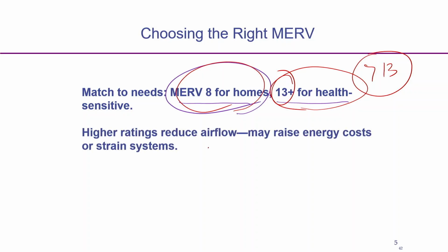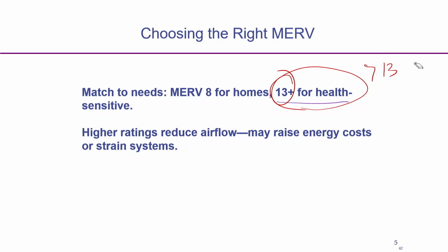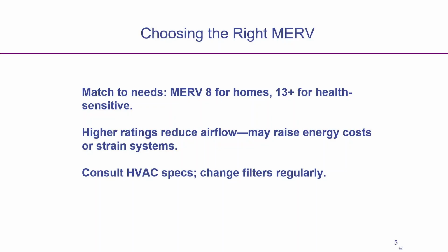A higher rating reduces the airflow. It may increase the energy cost, which we have to consider, and it will also strain the total filtration system. The pressure will be there, bursting pressure, and the filter can get damaged. So, we have to optimize between filtration efficiency and airflow. There are specs available, so we have to consult those, and we have to change the filters regularly.